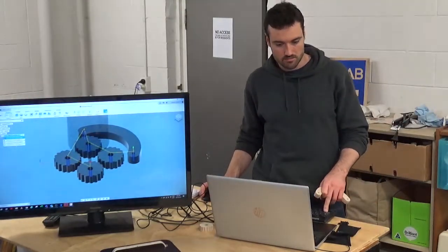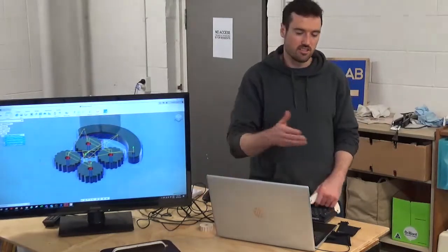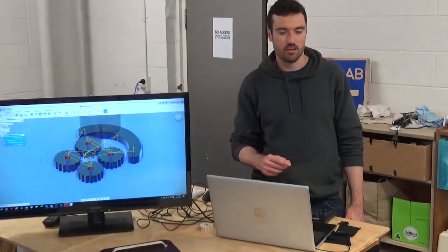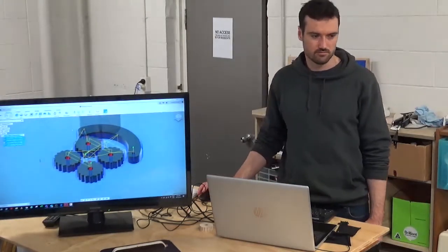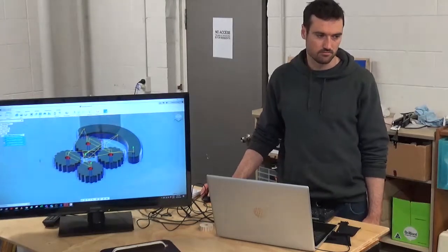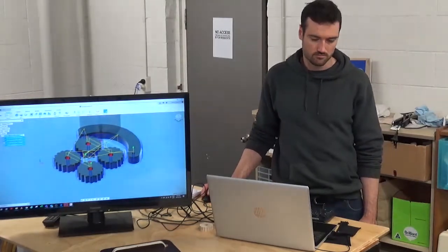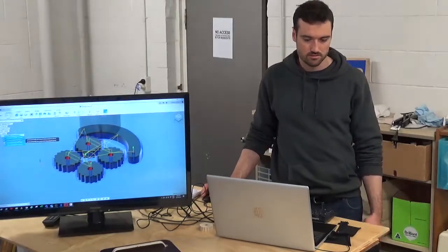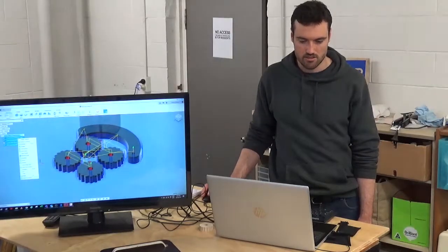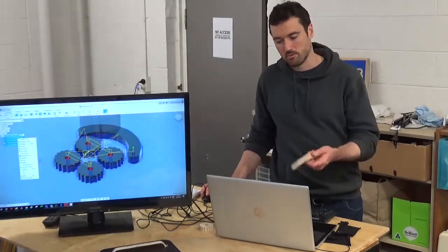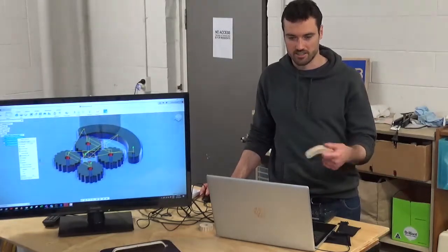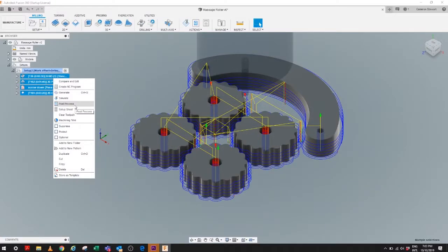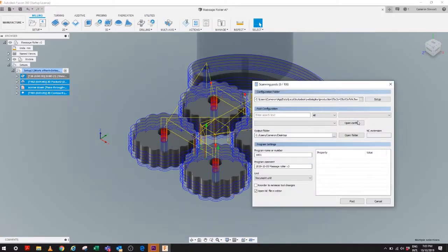So we fix the whole thing, you see? With this, you need to understand your material and how it's going to behave. You also have to be careful. You want to use this to drill the holes and pause first. Otherwise, you'll just put some screws in, and then you end up cutting through the screws and destroying the tool. So plan very much where your screws go and how you're holding it down at this stage, not later. So once you're happy, you can put the post process.